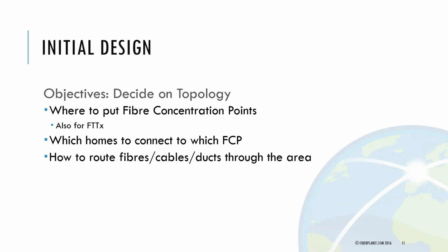And then also, how do you route everything through your area? So your cables, your ducts, where will you do trenching? Where will you use aerial? Where will you use existing conduits? So all of these questions already need an answer in your initial design stage.